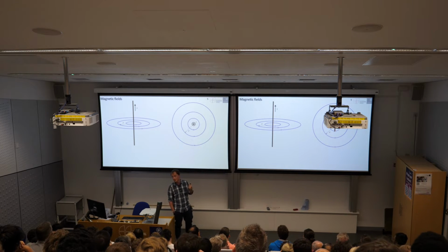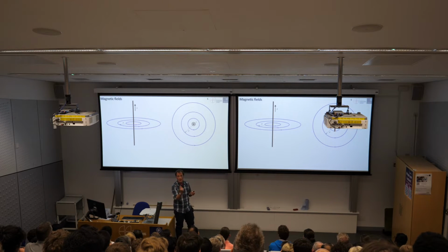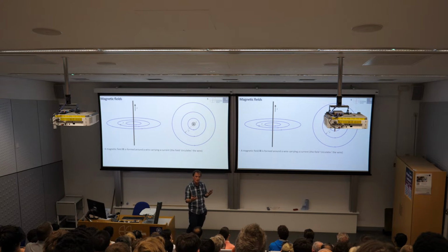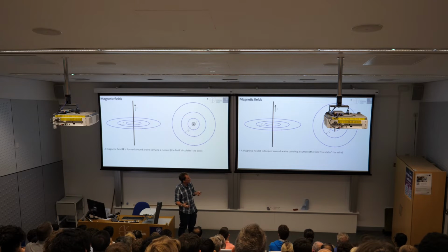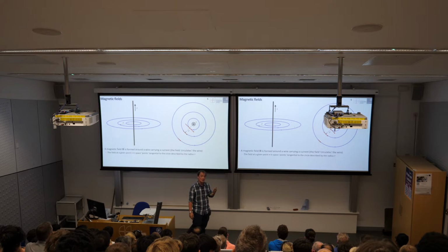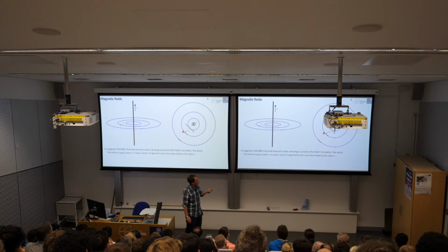Now, I'm sure many of you have seen this sort of diagram in physics. The black line is a conductor with a current flowing upwards. Around that wire, we develop a magnetic field. And we call this magnetic field the H field, capital H. It has a strength that varies with distance away from the wire. It drops off with a 1/r relationship. So what this means is the field is certainly not the same everywhere. Close to the wire, it's stronger, and further away from the wire, it's weaker, and it falls off as 1/r.